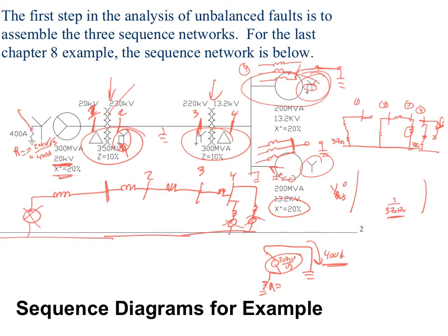So from the perspective of what's the reality of it, and this is one of those ones where people have just said it makes common sense that the utility is not going to own this 350 MVA GSU transformer. It ain't happening. They do own big transformers out on the utility line, like phase shifters or auto transformers to step up transmission levels or step them down. They do own those, but they would never own a GSU unless, well, we're deregulated. But if the transmission system owns the generation, like in the Midwest and certain parts of the West, that would be a different story. But at least on the East Coast, generators always own their GSUs.